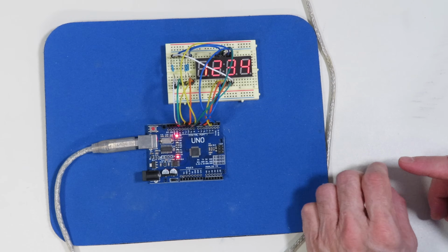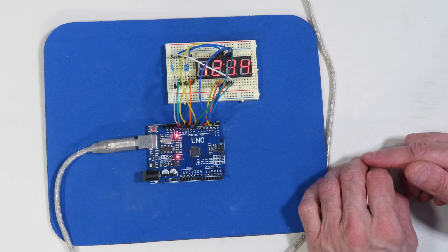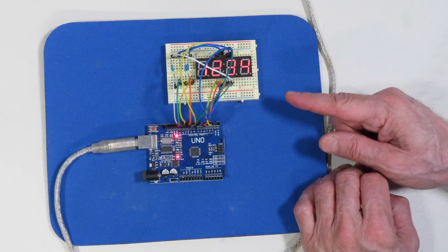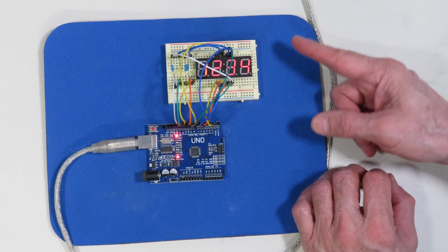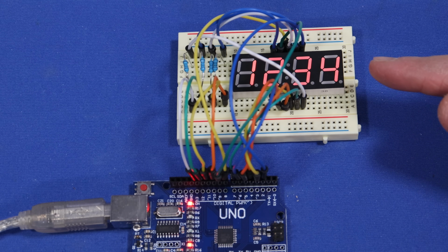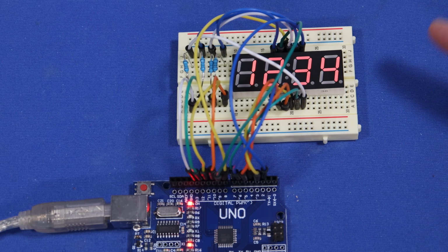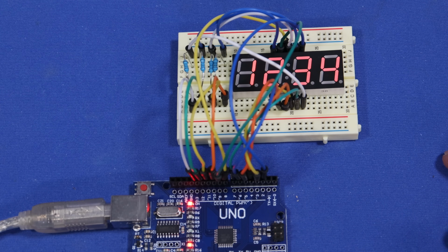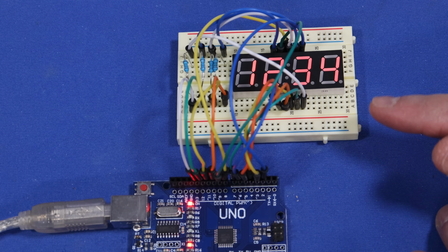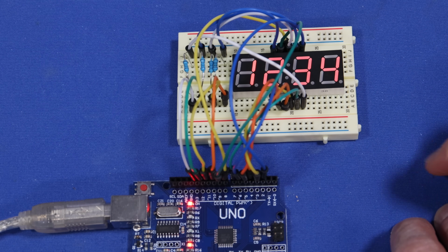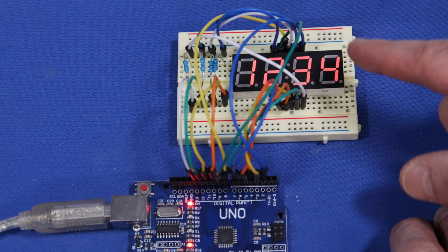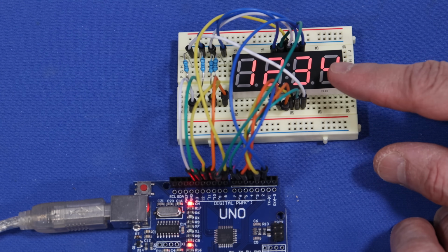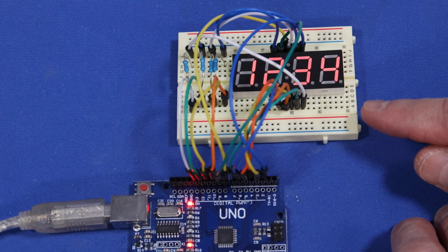So here's a demonstration of our 4-digit LED display being driven by the Arduino directly, and it seems to work pretty well. You can see our 4-digit number on the display quite clearly. Now the display is not as bright as it was when we were using the single digit, and that is because of the dropping resistors we have over here of 1K. And you have to remember the dropping resistors are on the display select lines, and so the current is being divided between all of the different LED segments and that single dropping resistor.